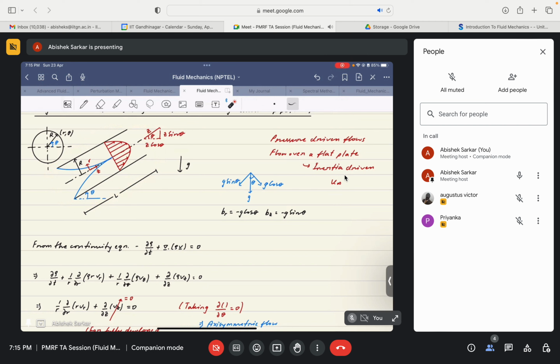So basically it is a region where the boundary layers from the ends of the pipe, I won't say both of the ends, it's a circular pipe. So it is the region where the boundary layer from the surface of the pipe develops and converges into the center line. And as I remember, as Professor Chakraborty discussed, why do they converge in the center line? It's mainly because of the symmetry of the geometry and the symmetry of the boundary conditions. It is because of this that the flow converges in the center line of the pipe itself.